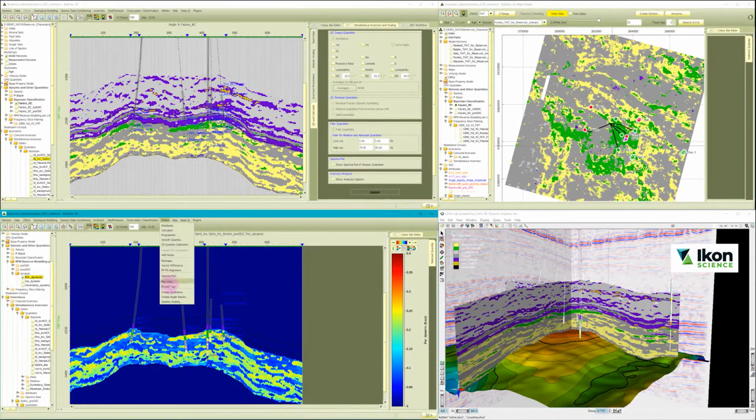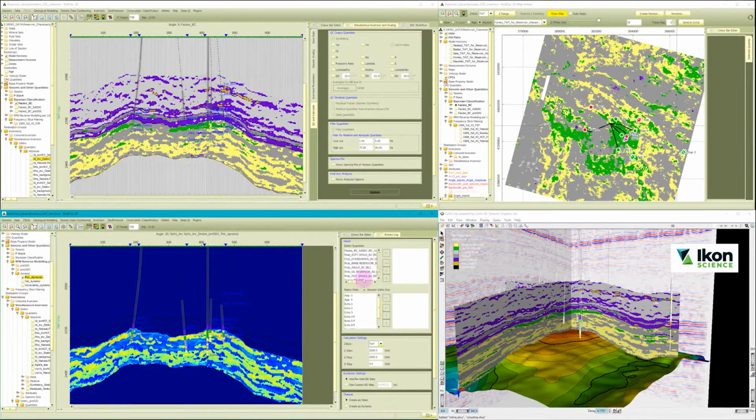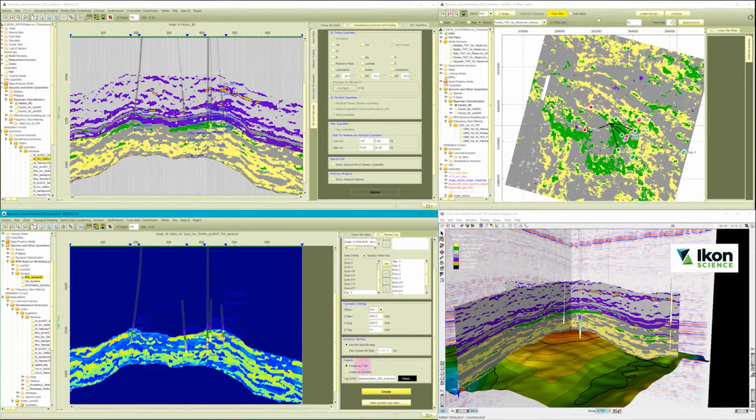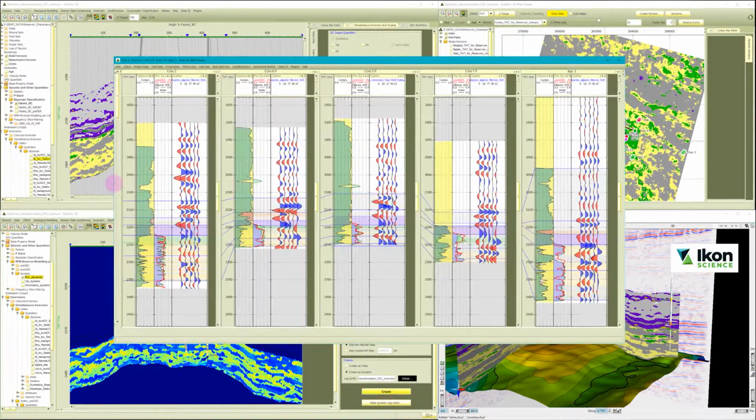Profiles at the well locations can be extracted from any interactive recipe within the session. Dynamic logs automatically update to reflect changes made to any of the recipes that go into generating that log. So for example, if I changed any of the seismic data conditioning parameters or any of the inversion parameters, the resulting porosity prediction as a log at the wells would update.